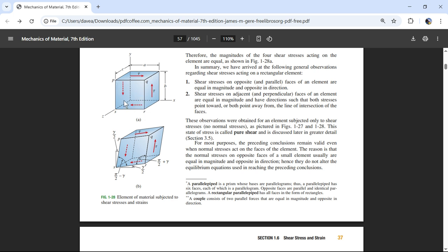Same thing with normal forces. If I had a 45 degree element, and I know that this normal force is now like 57, whatever, the other side is going to be the same. It's going to be 57. So it doesn't mean that I know this direction if I have an element at a 45. And so we would do the same thing to get the other directions: I would make a cut right here, cut all the way through this, and use this stress and then the bottom stress as my stresses.